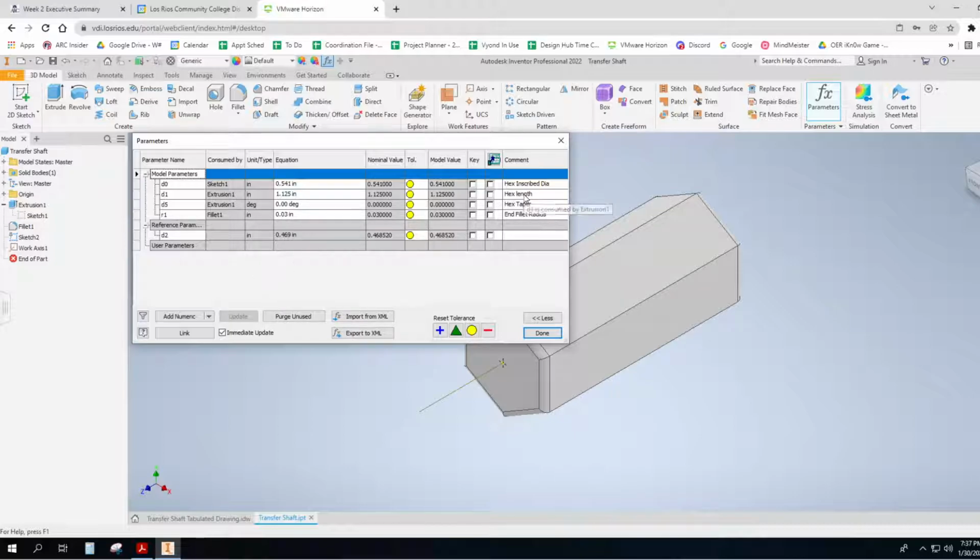Then there's the length, which you can figure out from the requirements that I gave you. We have no taper on this. Often you will see these with what's called a locking taper that will tap into place and lock. We are not doing that in here, and these fillet end radii are 0.03 inches. So that's the fillet radius, 0.03. And variations of this, as you know, you can change those.